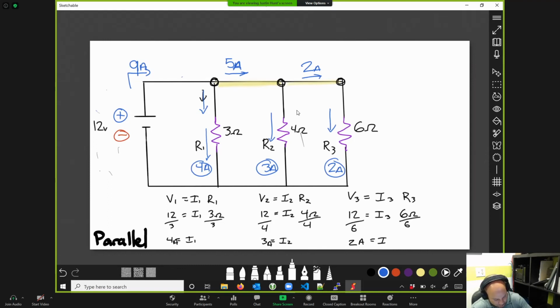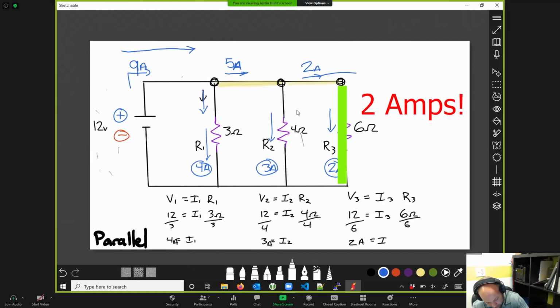So let's go back through this one more time. Coming out of the battery, we've got 9 amps of current. 4 we know, we already solved for, are going down this first path. We've got 5 left, and then we've taken 3 amps from that 5, and we know it's going down that path. So that means we only have 2 amps left. And lo and behold, that's exactly the amperage that we solved for that was going past R3. The 3 amps comes back around, and sure enough, that's exactly what we solved for.